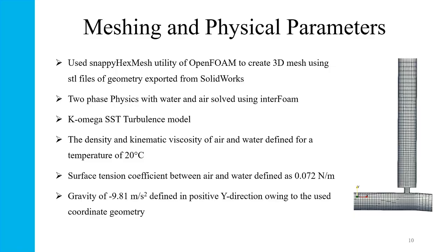The meshing of the geometry was done by using the snappyHexMesh utility of OpenFOAM, which uses the STL files of the geometry from SolidWorks and conforms the mesh to the surface. The two-phase physics of such a case with water and air was solved using interFoam, which is an OpenFOAM solver that solves the fluid problem with two incompressible, isothermal and immiscible fluids using a volume of fluid based multi-phase approach.